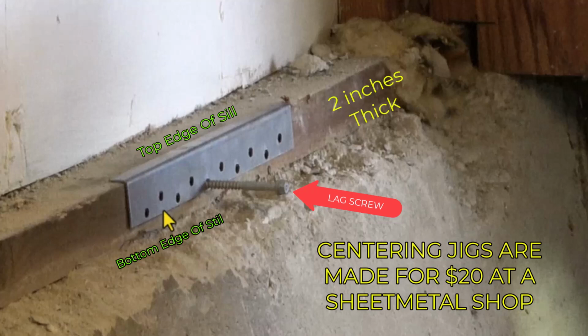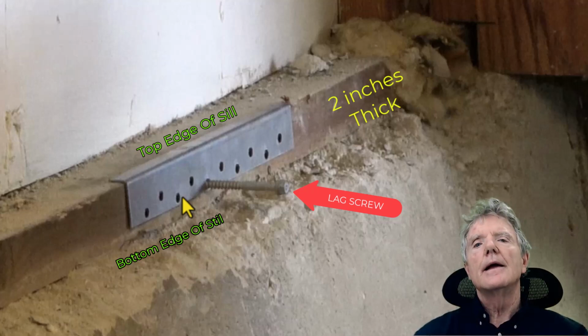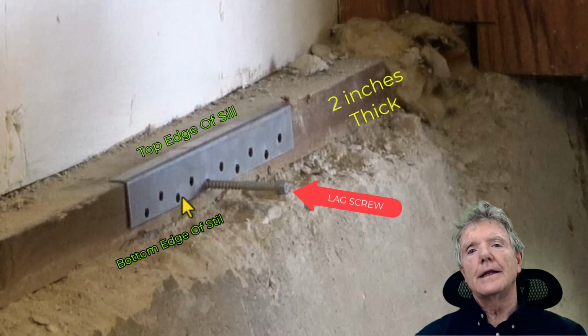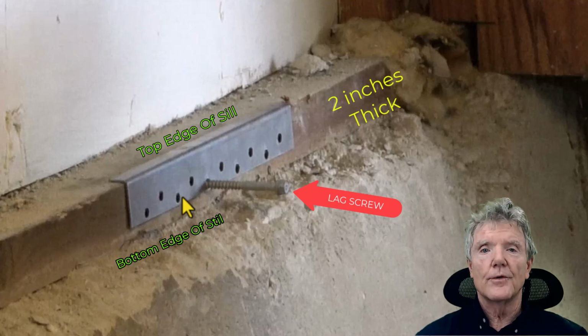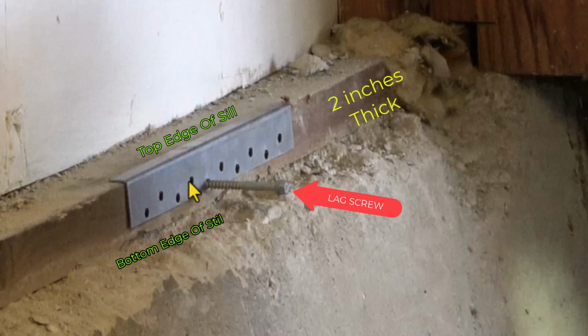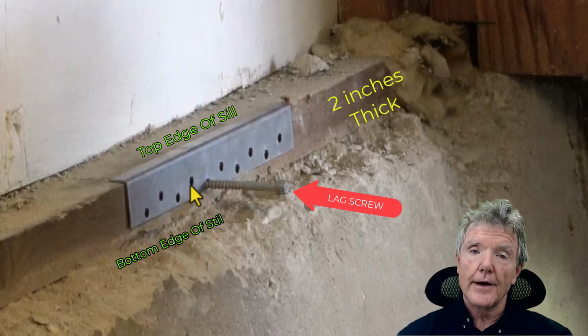So when we put this row of holes here, which are pilot holes to guide the screws, if we put them in exactly at these locations, at the spacings that we have right here, when we put in the URFP, the lag screws will go exactly where they need to go. Now, if someplace on your house we might find a 1.5 inch thick mud sill, because some of the older ones are that thick. In that case, we use this upper hole right here, because that's exactly 3/4 of an inch from the top. And if we have a 1.5 inch mud sill, it would be exactly 3/4 of an inch from here. And then once you're all done, your lag screws are right in the center where the manufacturer requires them to be.